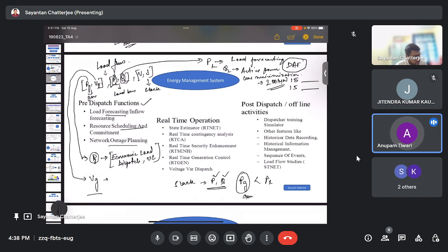So can we say now that storage, battery storage, and all the storage capacity we have discussed can be connected to the slack bus? Yes, it can be connected, but the storage batteries are themselves considered to be generator buses, because they are delivering loads. What I have told is that presently the participation factor based load flow is performed. Here, all the generators should take up the losses in their proportionate manner.